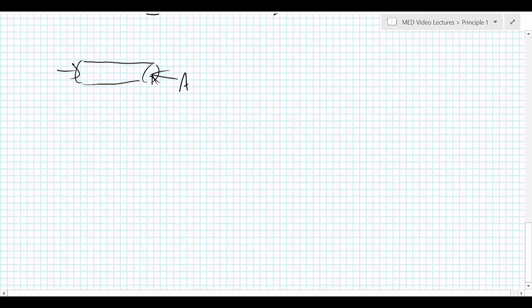So oftentimes shafts carrying gears will be under some axial force if they're helical gears or torsion gears, which are putting pressure on that shaft itself. Generally, this force is so small we're way, way below buckling, but it's always important to check.